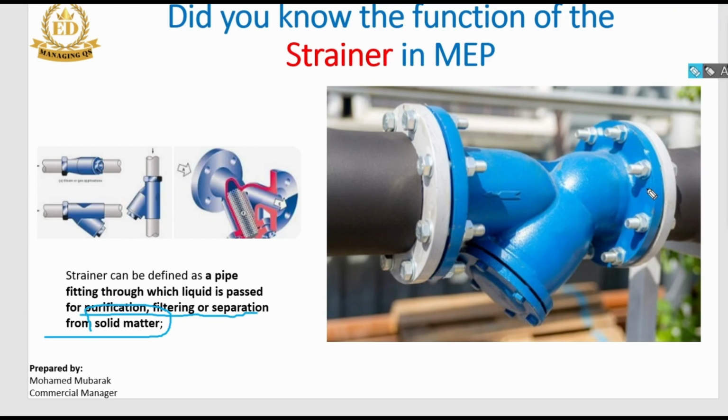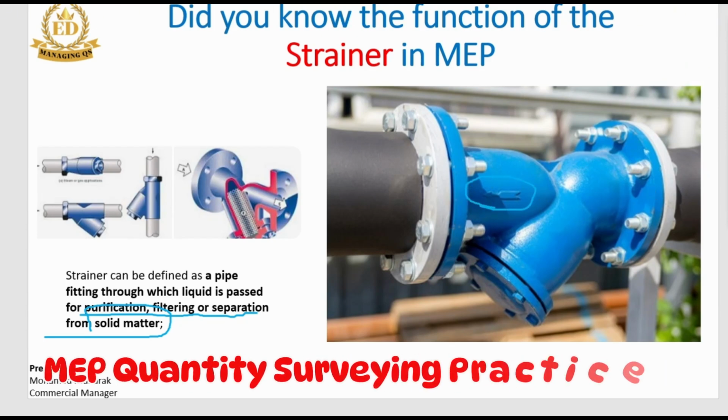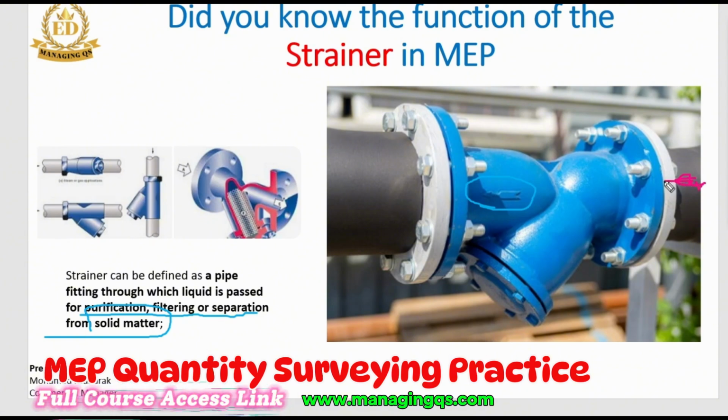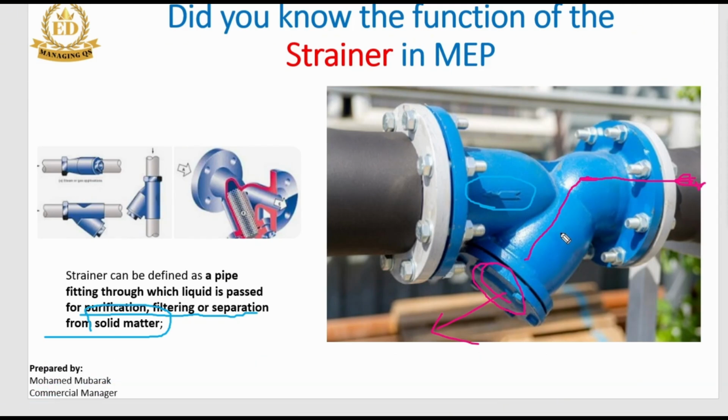You can see here the pipe flow goes this way. If any solid particles come along the way and reach this point, they automatically go downwards. So we can remove this cap and easily extract the solid particles from the pipeline. So this is the main function.